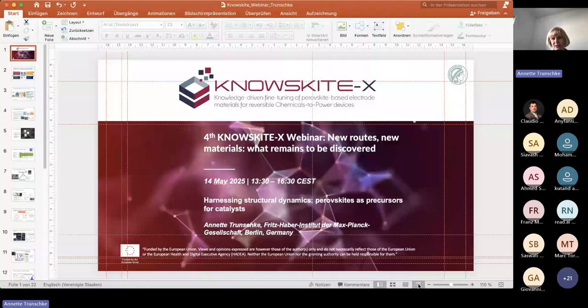So that are the white fields here, which we are not able to investigate in our study. And how we synthesize these perovskites, we applied a very simple technique. This is solution combustion synthesis. It is very easy. You mix your metal salt precursors with some fuel. We use glycine, and then you form a gel, such a foam, and then you heat this and initiate the